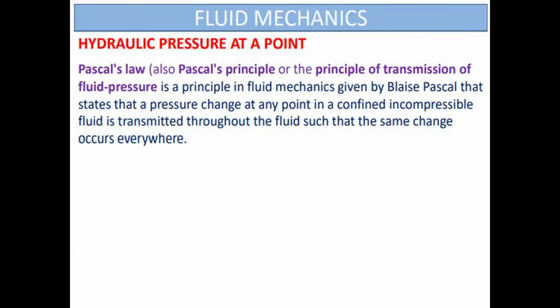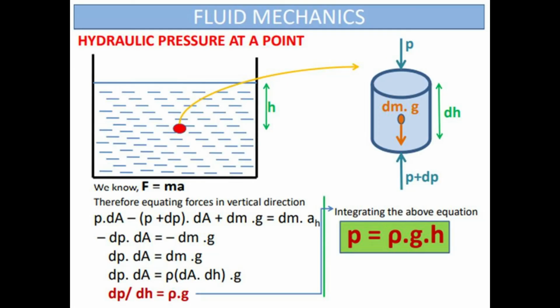This slide deals with hydrostatic pressure acting on a fluid. This concept is given by Pascal, hence called Pascal's law. Pascal's law states that a pressure change at any point in a confined incompressible fluid is transmitted throughout the fluid, such that the same change occurs everywhere. For this, a fluid molecule in static fluid is considered, at a depth of h from the surface, as shown in the figure. Now, pressure acting from the top and from bottom on the molecule, for the molecule to be in equilibrium are considered, along with its weight, acting in vertically downward direction. All the above parameters are shown here.